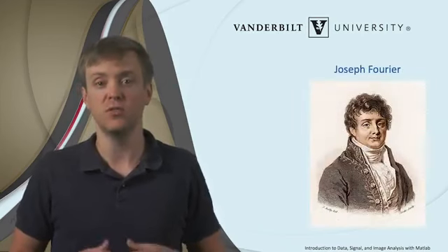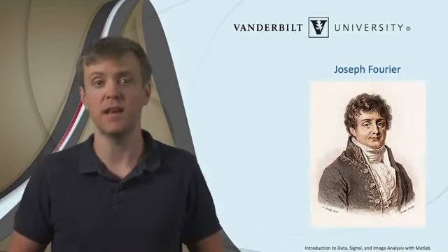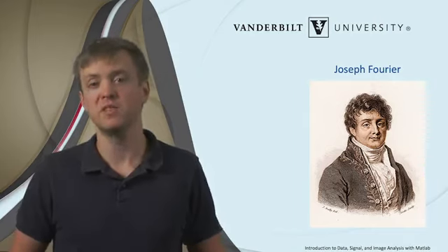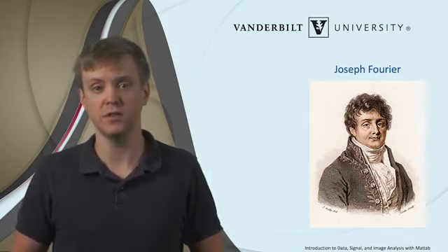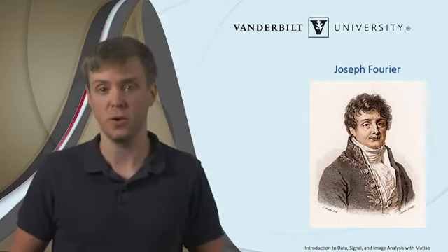So far, we have just visualized the waveforms and inspected whether there were lots of oscillations. However, we have tools that let us quantify the power of different frequencies contained in a signal. The main tool for this frequency analysis is called the Fourier transform, named after French mathematician Fourier. Specifically for discrete time signals, such as those we represent in MATLAB, this is the discrete Fourier transform.